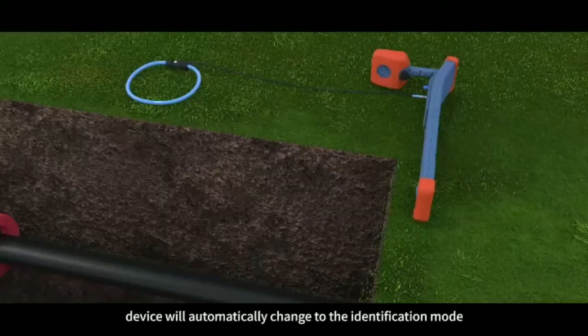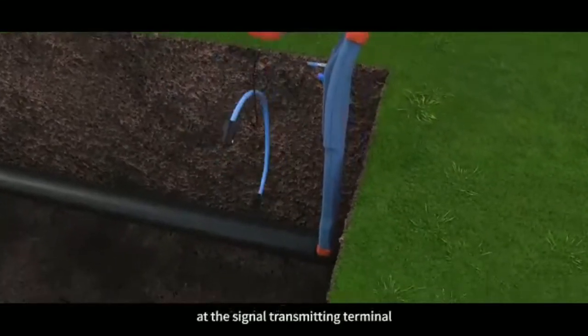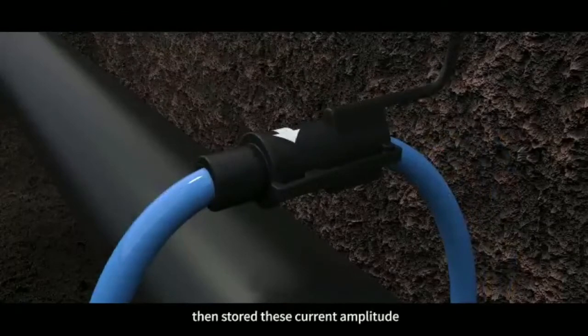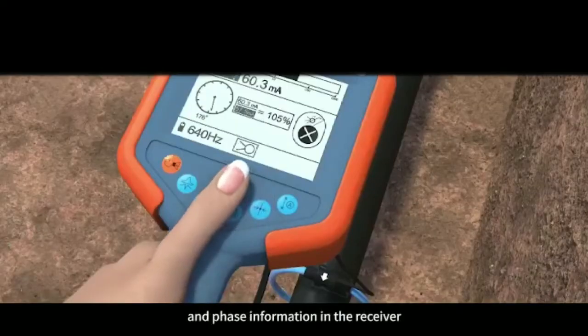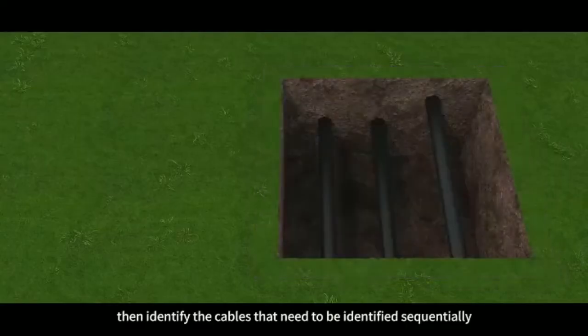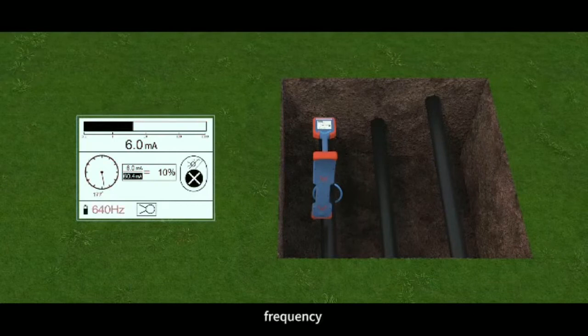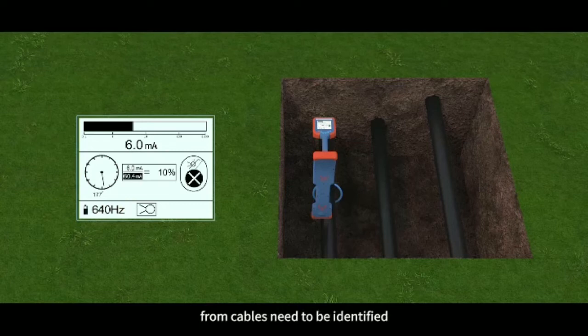The device will automatically change to the identification mode. Firstly, set the signal reference to the cable at the signal transmitting terminal. Then store this current amplitude and phase information in the receiver. Then identify the cables that need to be identified sequentially. The receiver will compare and distinguish the current amplitude, phase position, and frequency sampled by the flexible clamp from the cables to be identified, and give an accurate identification result.